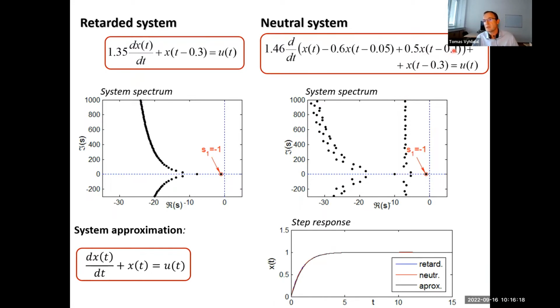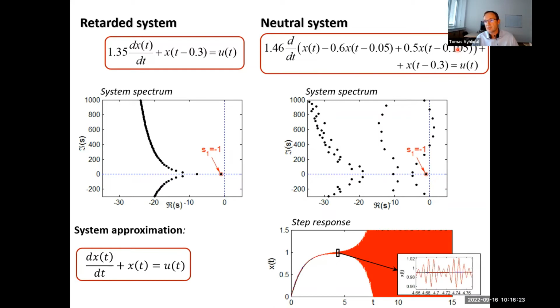But see what happens if we perturb this delay slightly. The neutral chain is deflected, and in fact we have infinitely many roots entering the right half plane of the complex plane. The system becomes unstable due to high frequency roots. It doesn't matter how small this perturbation is. The smaller it is, the higher the frequencies at which stability will be lost.